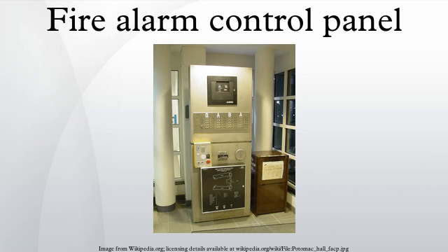A new alarm initiation while the alarm is silenced will take the panel out of audible silence and reactivate the notification appliances. Drill, also known as manual evacuation, or evacuate. On panels containing this function, the drill indicator shows that the alarm condition was activated from the fire alarm panel, often in order to conduct a fire drill. When an alarm is initiated for a drill, the fire department or monitoring company is usually not notified automatically.